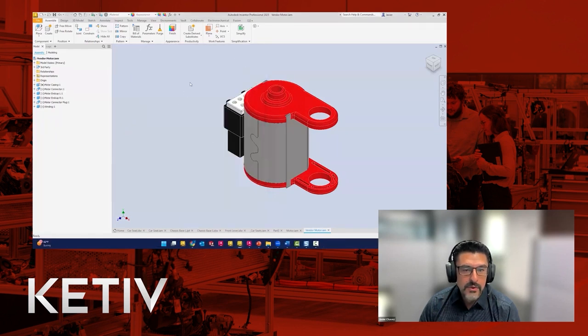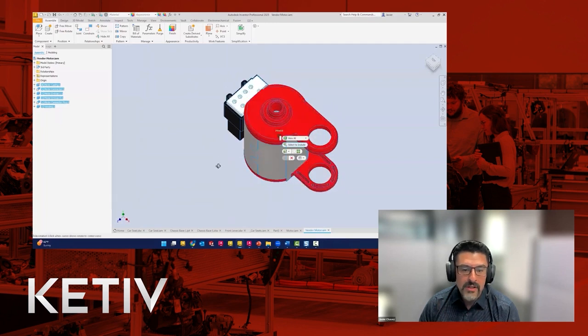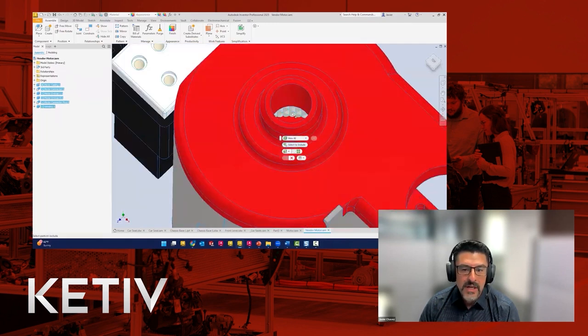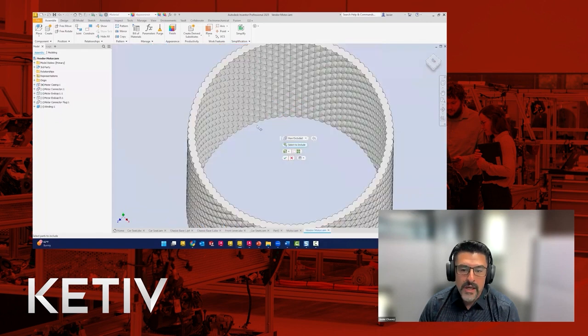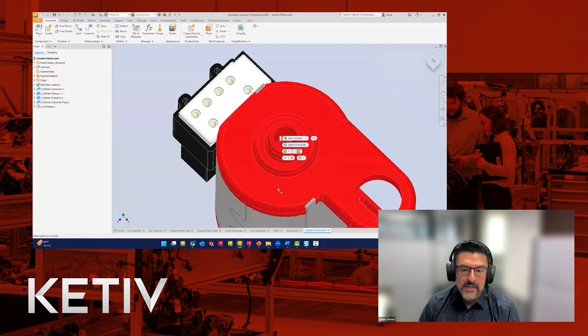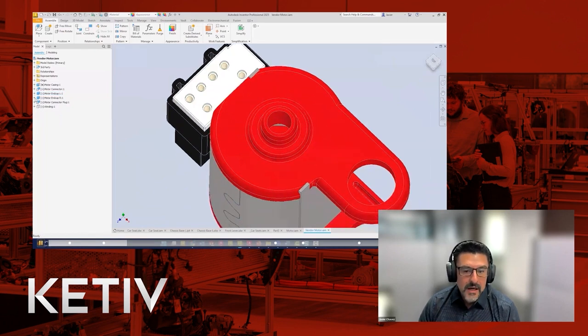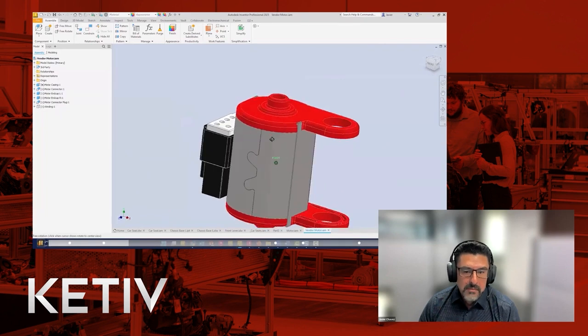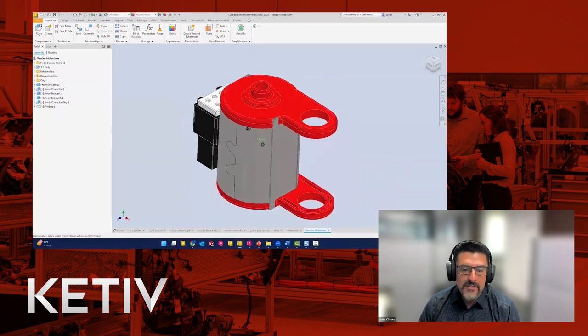We're going to use a series of tools, and within the assembly environment, you could start editing what you really want to maintain in this assembly. And so that internal component, when I launch it, I could pick that edit view tool to say, do I want to include it? Do I want to exclude it? I could change my view to see what's excluded, and that's what we're going to take out. And simply by clicking OK to that, on the left-hand side, you can see the winding is now turned off. So, step 1 in simplification, get rid of stuff you don't need.